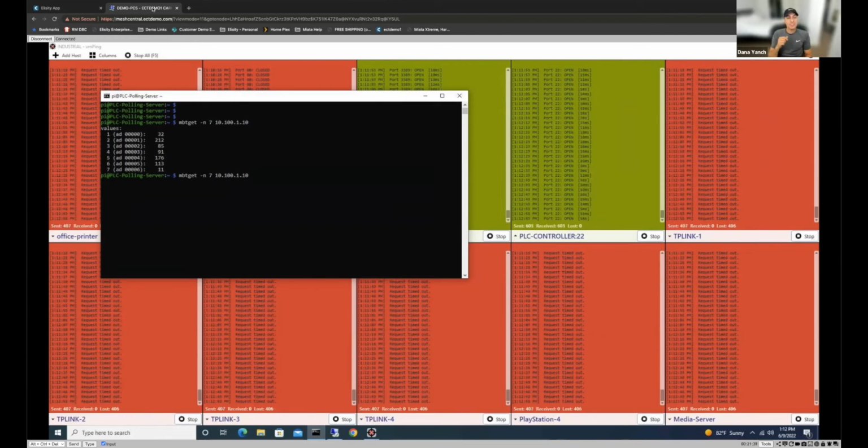This allows us to completely decouple identity from any network construct. All you did was match on attributes of those PLC controllers or Modbus devices. In this case, maybe you matched on vendor, model, or device type, and that was enough for the system to pick up the identity of that device and then enforce this least privileged access policy that you created.